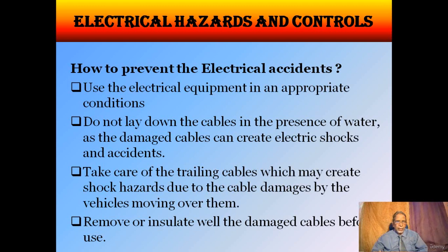Take care of trailing cables, which may create shock hazards due to cable damage by vehicles moving over them. You should take care that cables should not be laid down where vehicles pass over them. Remove or insulate damaged cables well before use. Before using a cable, check it thoroughly for damages. If there are some damages, remove those cables and use good cables.